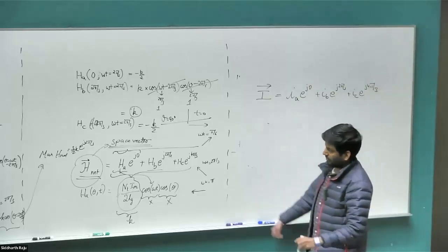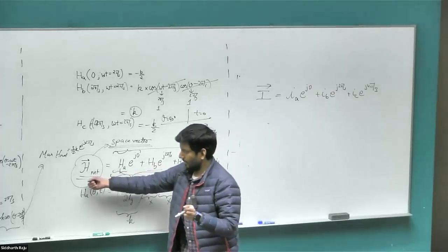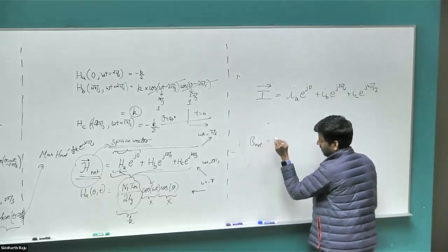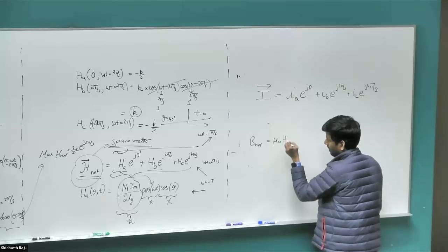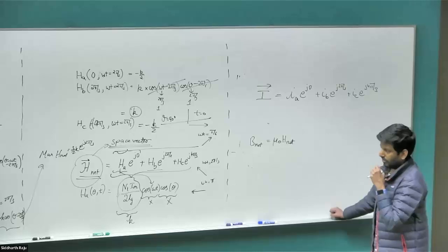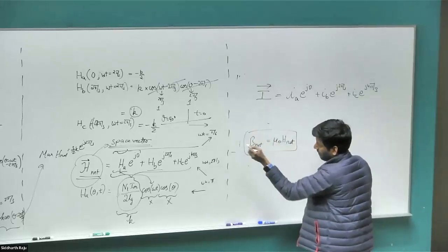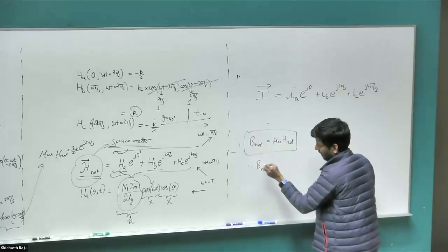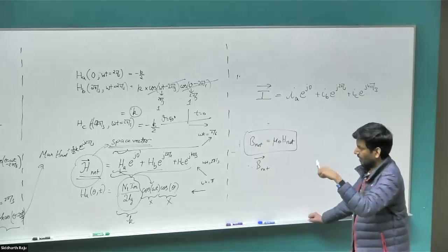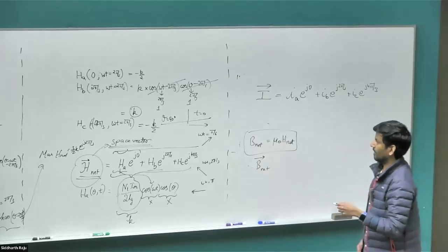Again, in the case of the H field, the B field is just mu naught times H net, as long as the core isn't saturated, otherwise superposition itself doesn't apply in the first place. We are never going to consider saturation in this course, so don't worry about it. In the case of B, you can write a space vector for that as well. It indicates where the B field is at its maximum at any given time, and the rest of the B field in the air gap you can directly infer from this single value that I give you.